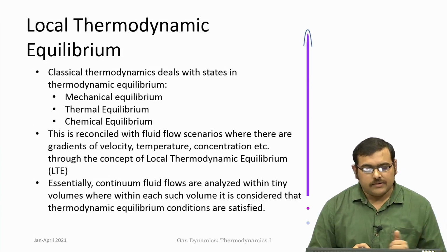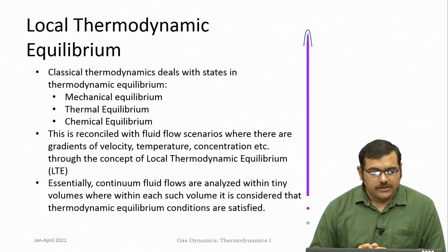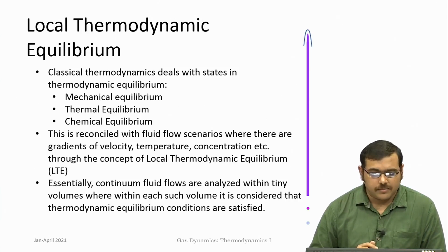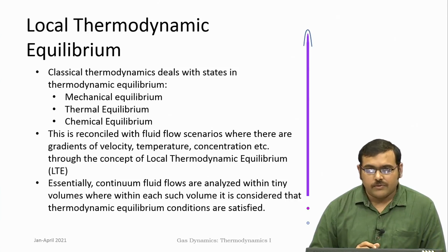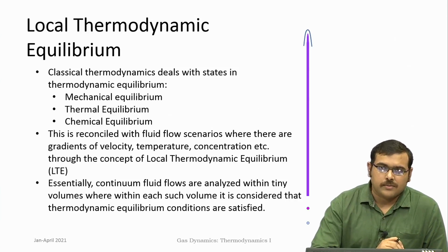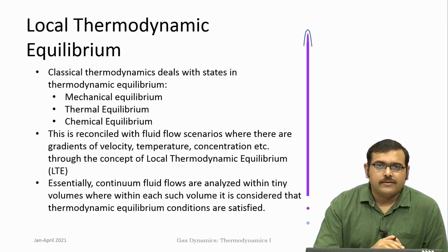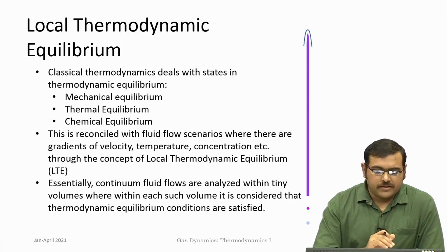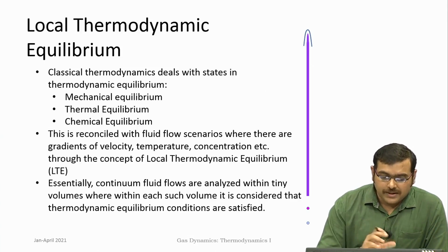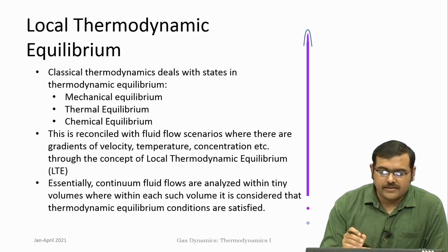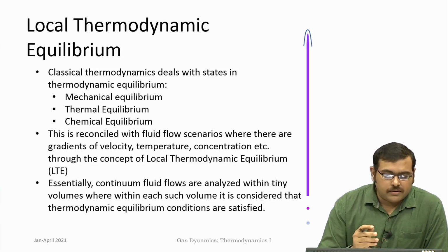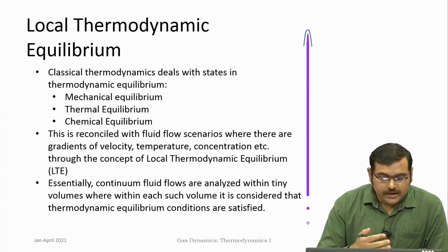So another important concept that comes here is the local thermodynamic equilibrium. Classical thermodynamics deals with states that are in thermodynamic equilibrium, and thermodynamic equilibrium means that the two states that you are considering, state A and state B, have to be in mechanical equilibrium, thermal equilibrium and chemical equilibrium. Mechanical equilibrium implies balance of forces.